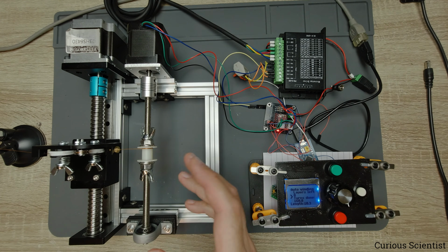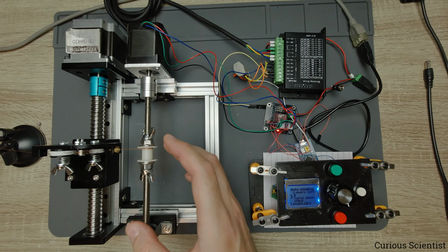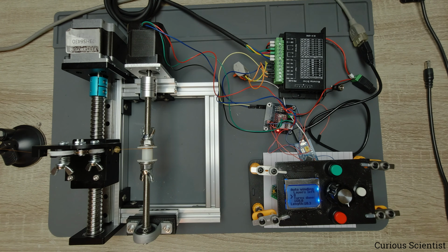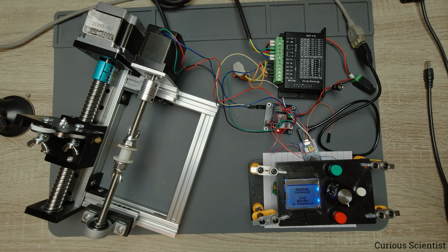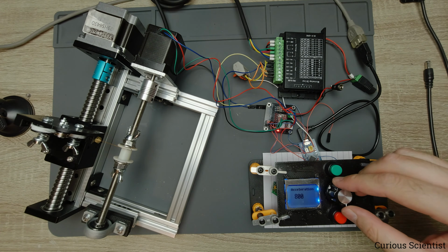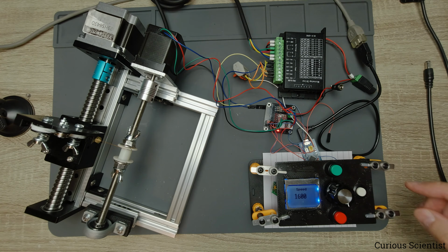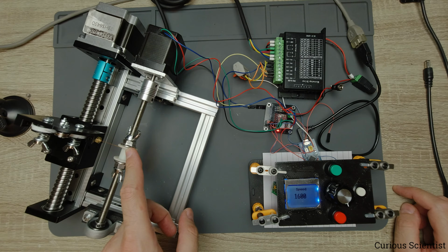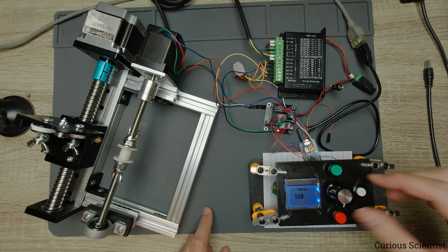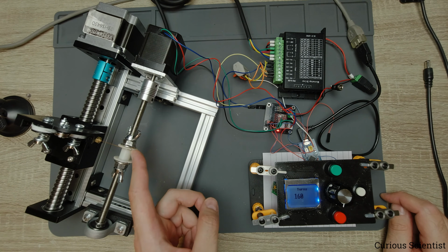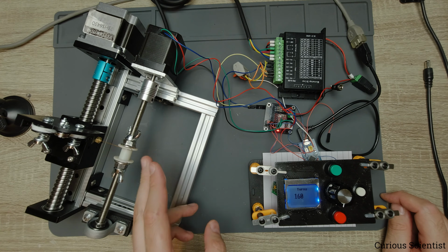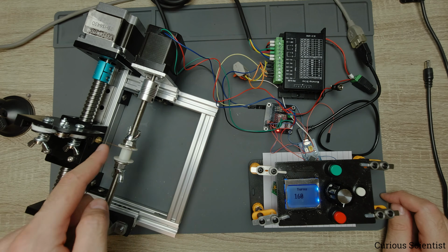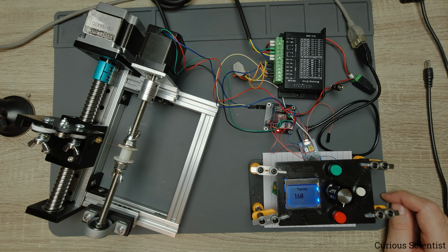And before starting this, I will also prepare another camera to give you a close-up picture of the winding procedure. So I prepared everything. I restarted the microcontroller, and I didn't change anything. So we will go 60 RPM or 1 turn per second on this part, and then I know that we want 160 turns, so that should be 4 layers, but I'm not sure if we will be able to finish the 4 layers because of the irregularities on the wire surface.